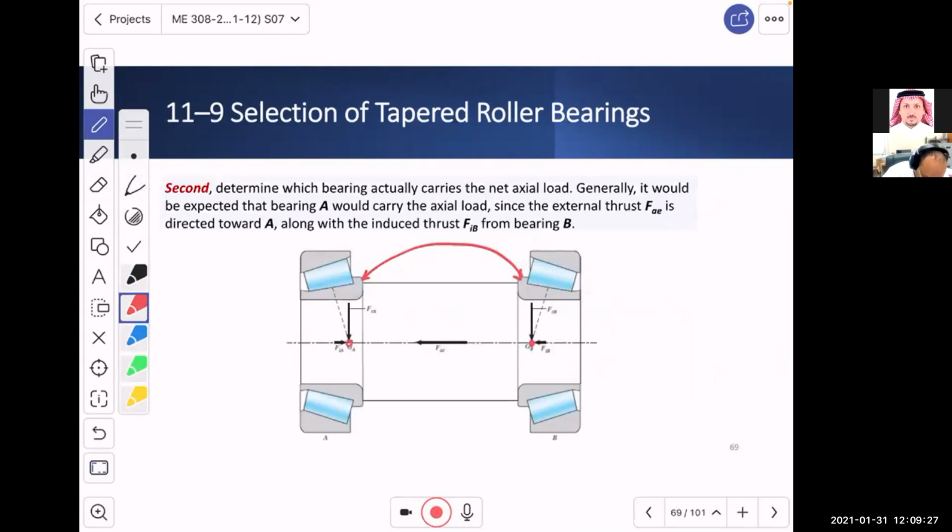Good. So there is a radial load acting on the bearing like this, but when it goes to the roller, this load will come in here, and then it will get converted into a radial load and axial load. So we have this one, since it is opposite, it will go in the opposite direction. And of course, the radial load will stay down, okay?